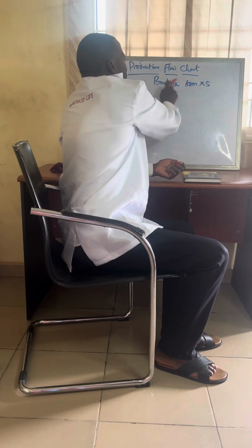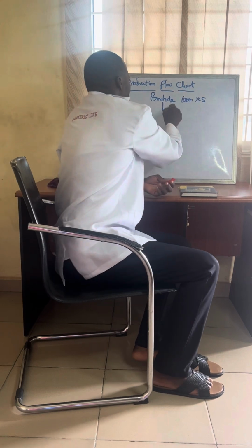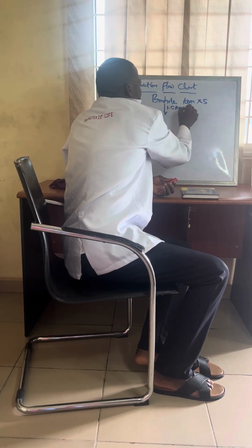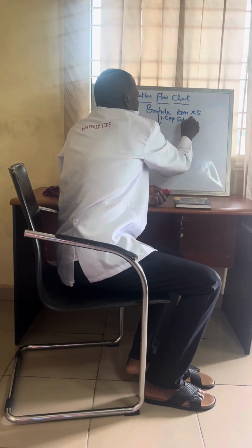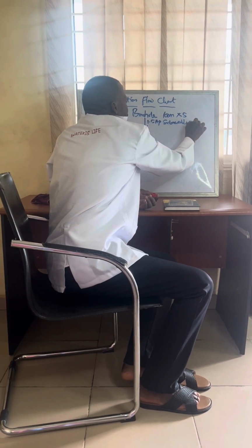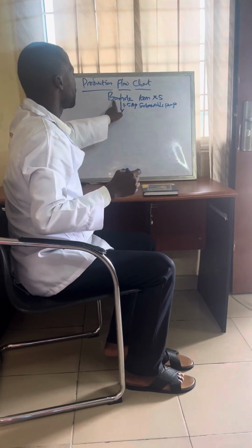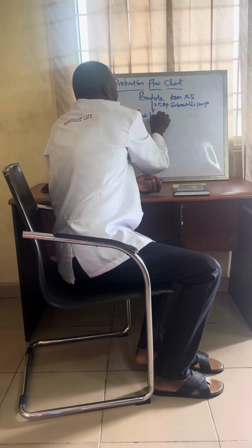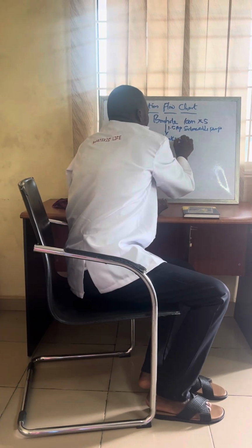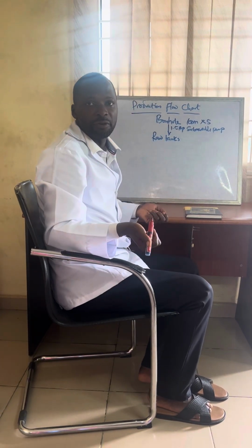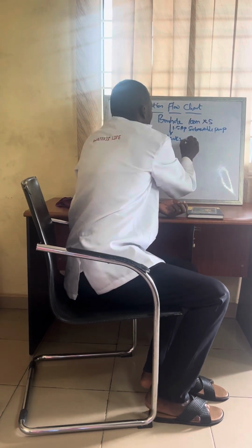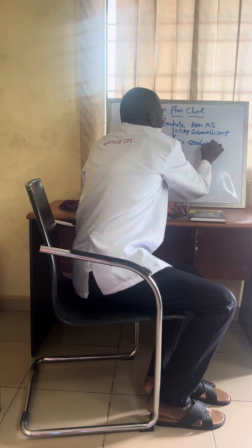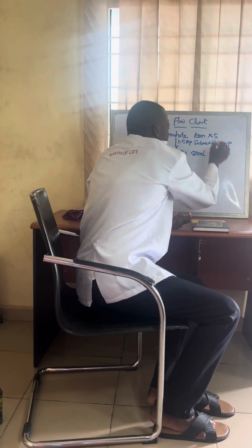Now, what pumps this water from the borehole? Let's assume you have a 1.5 horsepower submersible pump. Now that is pumping this water from the borehole. Where is it pumping it to? It's pumping it into your raw tanks. Probably you have up to 10 raw tanks. First of all, you need to let us know the volume of your raw tanks. Let's use the least of it, which is 5,000 liters, times probably 20.